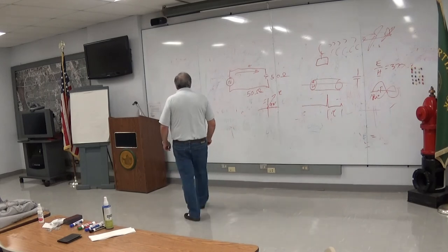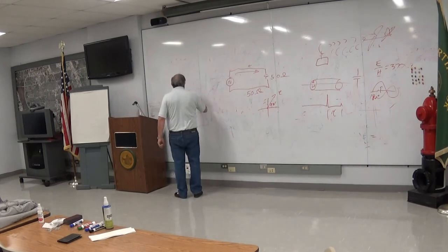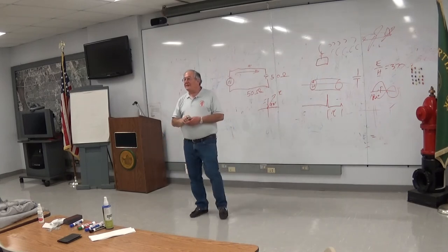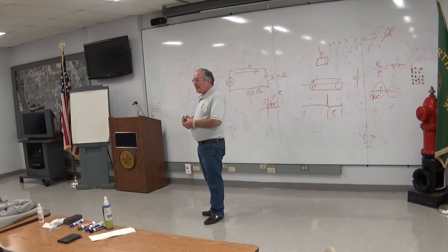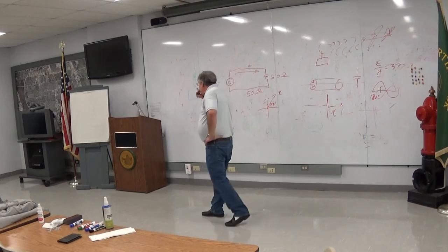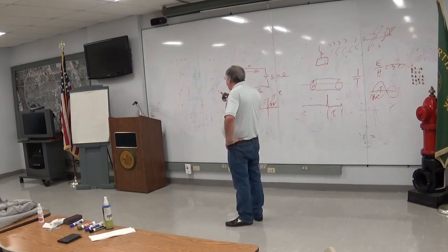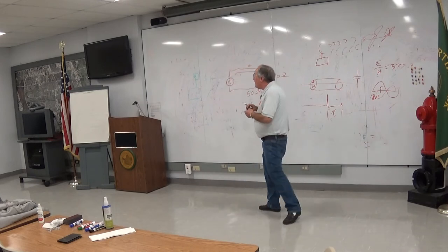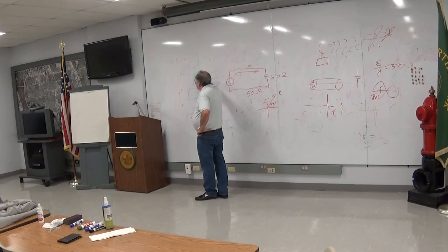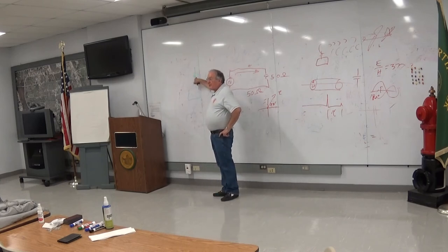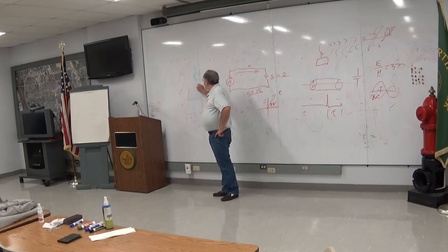When you have these 5/8 wave elements here on a car, there's a coil in the middle. And what they've done is, they've had 2 elements, basically, they took the quarter wave and they split it up. And why 5/8 works, I'm not sure, but because it is what it is, this coil is actually adjusting for the shorter part, the shortening of it. There's also a coil down here that does the same thing.